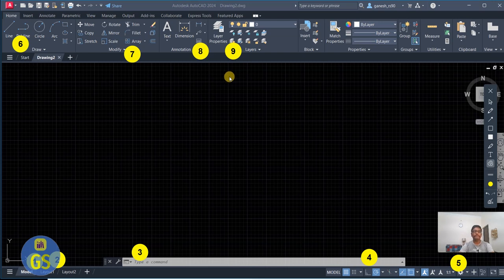So this will be highly useful when you make a plan and when you execute some sketch using AutoCAD. So layer manager will be highly useful for it. The next one is all about blocks and attributes. So you have some family blocks; if you want to insert furniture or any kind of equipment or drawings, you can bring it in as a block and insert it in the drawing.